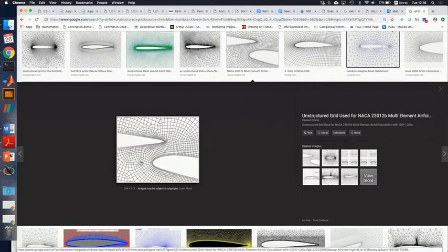Computationally, this is a huge drawback, because now we don't have this nice vector or matrix where we can run through i and j very easily. Every time I want the derivative at this point, the first thing you have to do is loop through everybody and find out who your neighbor sets are, and then figure out a good way of computing derivatives in these oddly shaped cells.